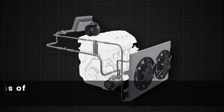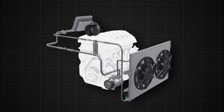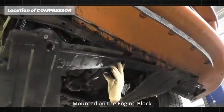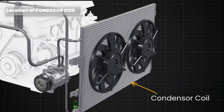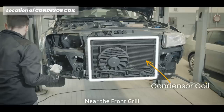First, we will see the locations of all components and after that their functions. The first one is the compressor. It is mounted on the engine block, usually at the front of the engine block, or mounted on brackets attached to the engine, near the radiator and condenser. Condenser coil, located in front of the vehicle's radiator, near the front grille.